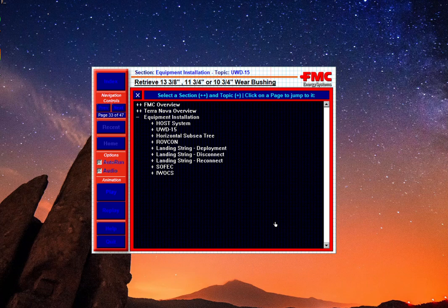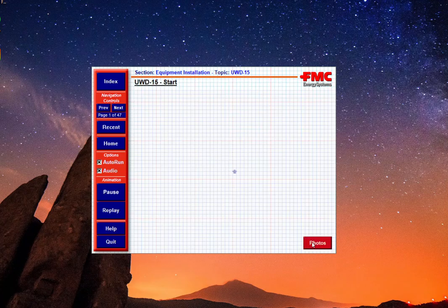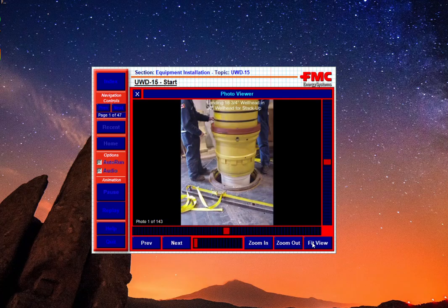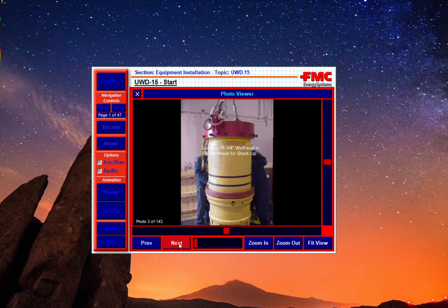Typically, what she didn't say is that you actually have to clean a little bit. And then you run casing, and the casing hanger lands on top of the previous casing hanger, and you're setting the seal assembly in the same way as what you did. Let's see if there are any interesting pictures here. Yeah, it's the same basically.